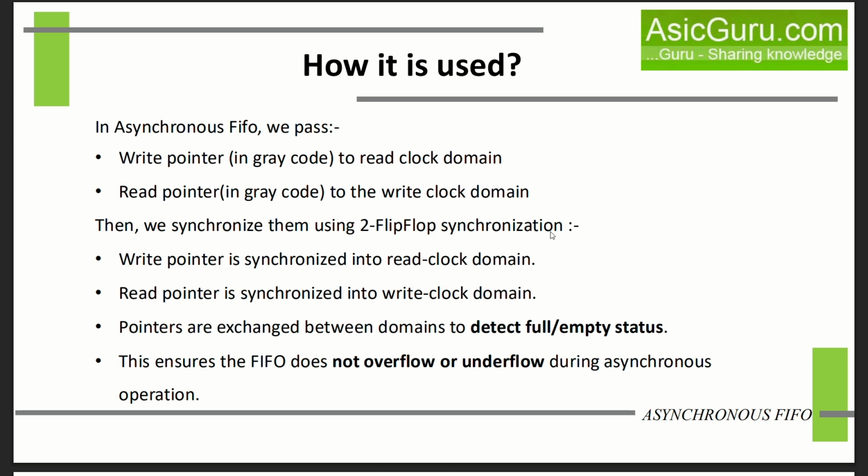The question arises why pointers are actually exchanged. Pointers are exchanged between domains to detect the full and empty status. This ensures the FIFO does not overflow or underflow during asynchronous operation.